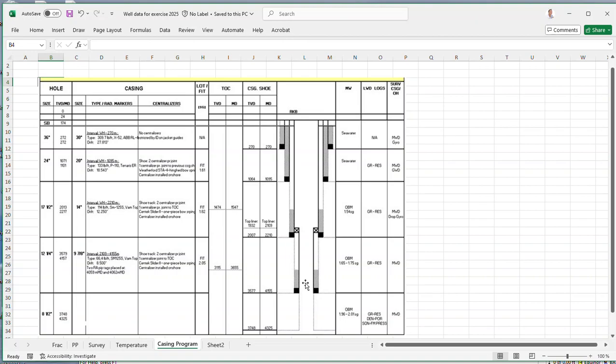Now this is a very special well construction. You see there's an 8.5 inch section going through the reservoir. There's a liner and the 14-inch casing that we are installing. As a matter of fact, if you place the production packer down here or if you place it here, regardless, it's going to be exposed to the annulus, meaning it's going to be a production casing.